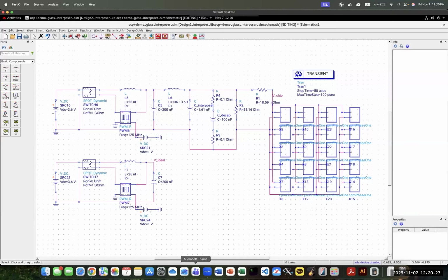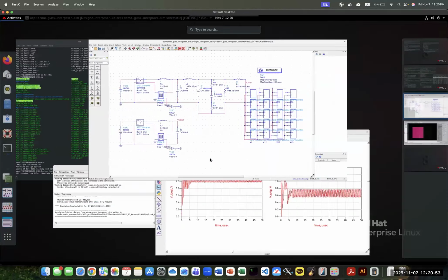Would that be multiple CPM models, or a piecewise linear CPM? The CPM model by itself is like a SPICE netlist, basically RLCs with current waveform. So the current source could be an equation, you're saying? No, it's an actual PWL.